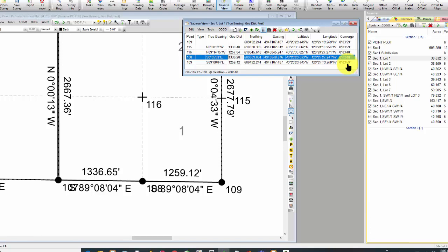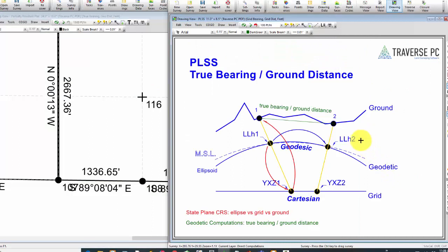Okay, when I did the webinar last month, one of the comments someone wrote back is, I really want to see ground area versus grid area. And what they were talking about, and I'm going to jump in and talk about that next year, is, remember I said the BLM doesn't want the area down here on the state plane grid, because what was conveyed in the patent was so many acres for that aliquot part at the ground.